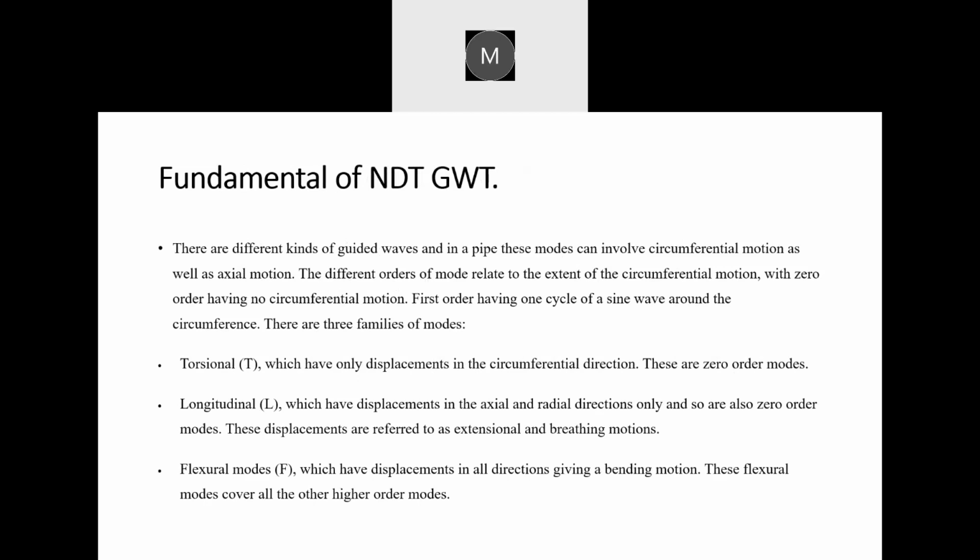Okay, these are the fundamentals of guided wave testing. There are different kinds of guided waves in a pipe. These modes can involve circumferential motion as well as axial motion. The different orders of mode relate to the extent of the circumferential motion, with zero order having no circumferential motion and first order having one cycle of sine wave around the circumference.